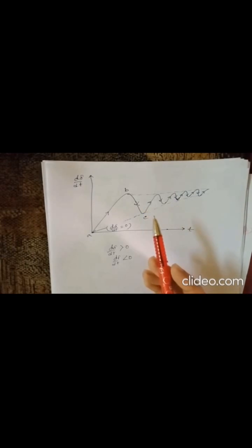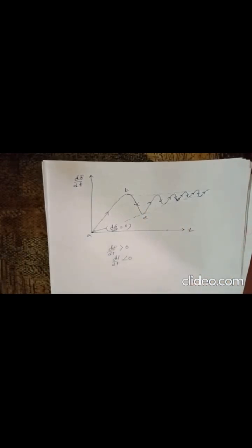Now the rotor oscillates about the rotor angle del 1, the upper limit being del 2 and the lower limit del 0. So look at this previous picture. Upper limit del 2 and this is the lower limit del 0. Now for the steady state condition to be reached, Pm equal to Pe equal to P max sin del 1. That means the accelerating area should be equal to the decelerating area.